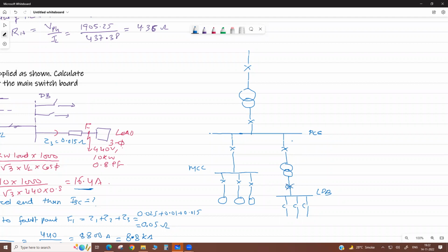Why do we use a lighting transformer? For isolation. Supply isolation. First is isolation. Why? It isolates your lighting loads from the main loads, the important loads, motor loads, process loads, okay? This is the main utility load. Why do we separate, meaning isolate?